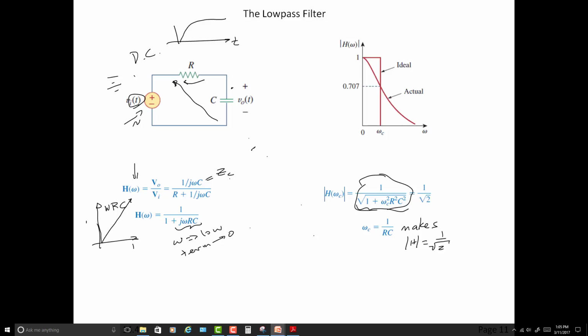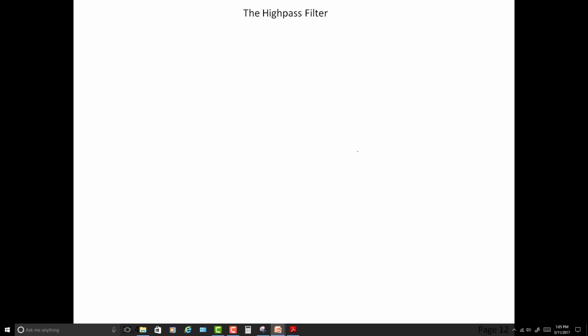If this is what is on the capacitor, and the source is up here at some constant level, then somehow the missing part must be happening across the resistor. That's a voltage divider going on, right? So let's get the transfer function across the resistance of the output voltage to the input voltage. Pretty simple in the same way.